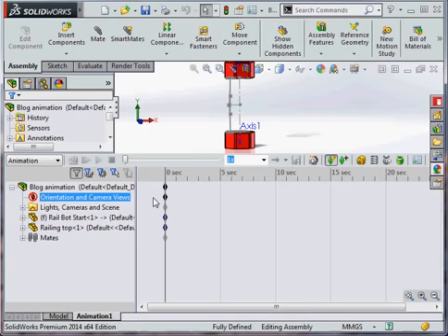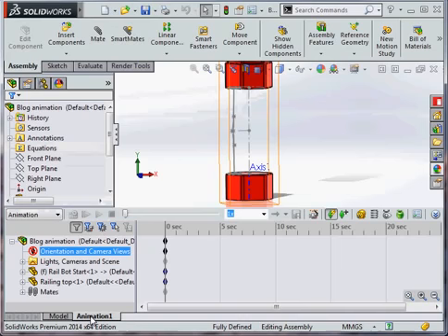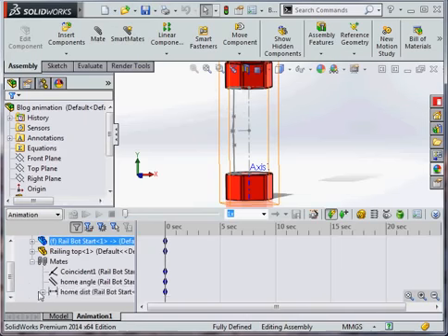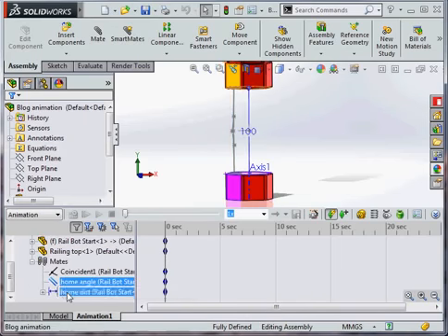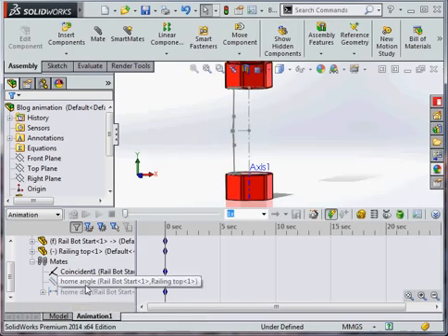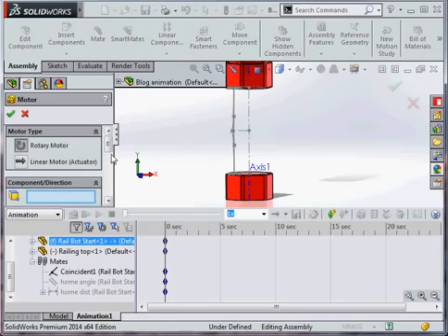and I am going to generate the movement. So we can see my assembly tab that we've activated allows me to manipulate my mates independently. So I'm going to suppress my home mates. So this top piece is now free to move up and down and to rotate. And that's how we're going to manipulate the spline, because it's always going to be a fixed length. It will deform the way I want.